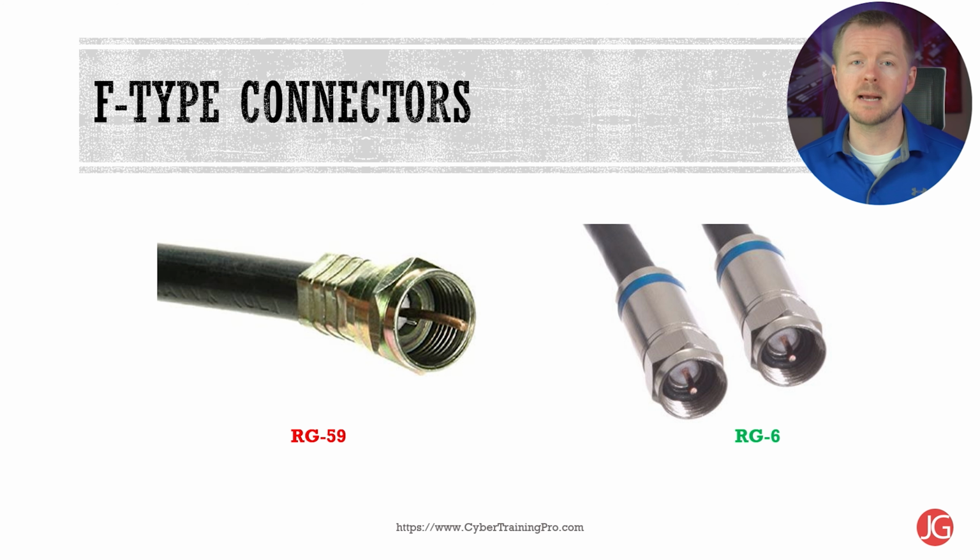Now, there's two primary types of coaxial cables that you'll probably see: RG59, which is typically used for cable television, and RG6, which is much more common because it's a thinner cable. Coaxial cables have a radio guide or an RG rating for a quick reference of the type of coaxial cable that it is, but the important measure that you need to know is the ohm rating, which is basically a measure of resistance. It means how much that cable is actually resisting the flow of electricity. Both RG59 and RG6 cables are rated at 75 ohms.